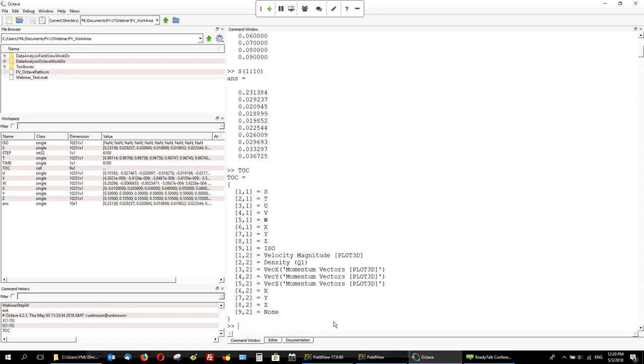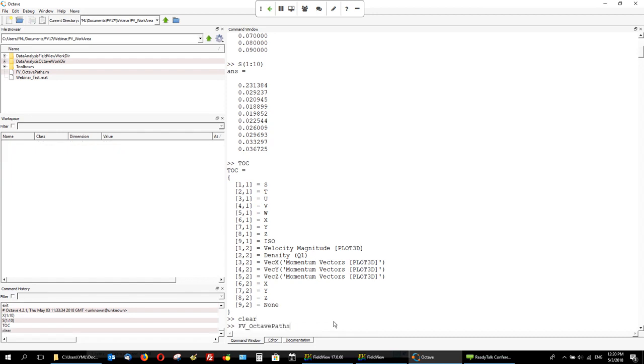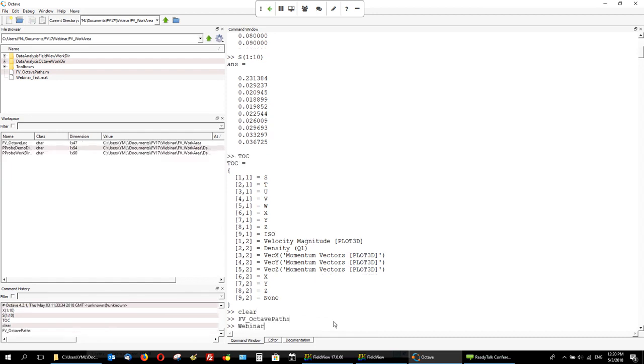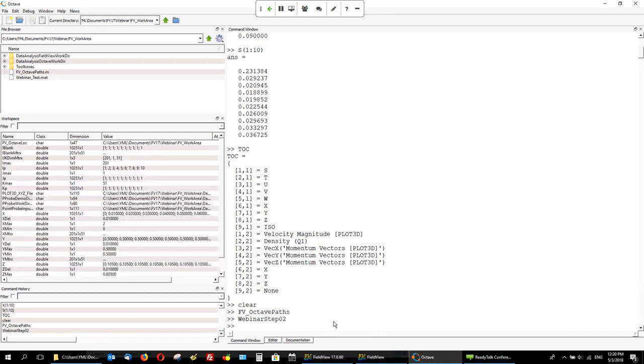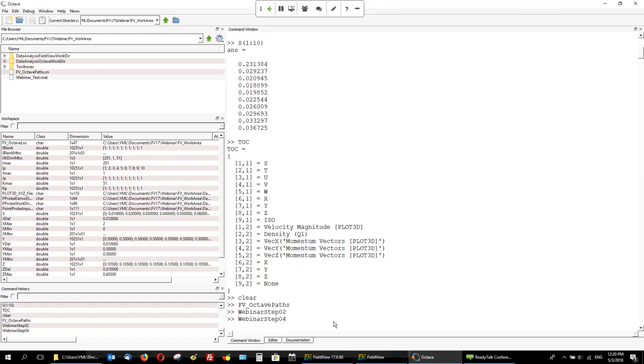Okay? All right, so let's clear that. I will just quickly reset my environment here to be able to rerun my SVD analysis. All right, and from that point, I will launch a script. So again, I don't want to go into the details of how it's been coded, but if you're interested, it's all scripts that we can provide to you from Intelligent Light. And what this next step is doing is that it's going now through 900 MAT files that we've exported initially. And we're going to compute the singular value decomposition. And at the end of the process, Octave is going to give us a plot with the most significant modes being visible on the plot.